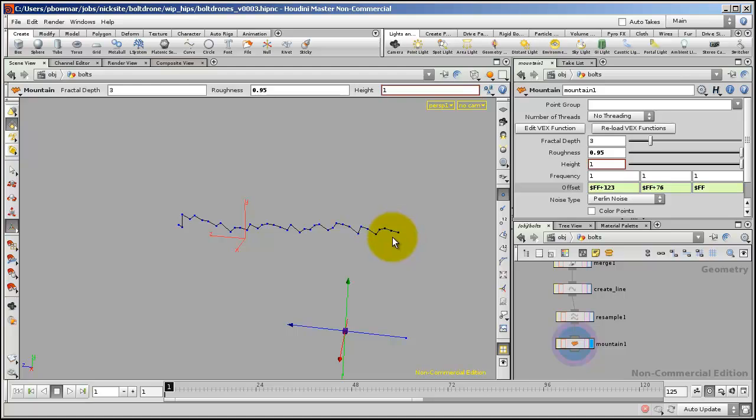To get the beginning point and the end point to blend in an intuitive and artist-friendly way, we'll use a ramp, and specifically we'll start to use a particularly powerful piece of technology called VOPs. VOPs is basically a language used to modify point attributes and positions, but you don't have to code it by hand. Like everything in Houdini, there are nodes to put together.